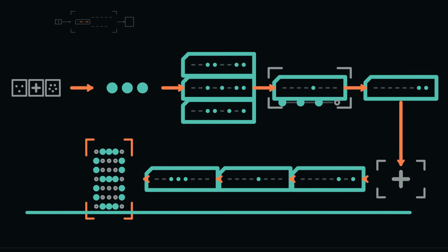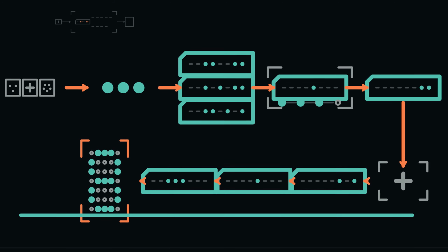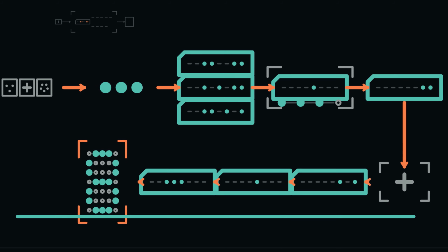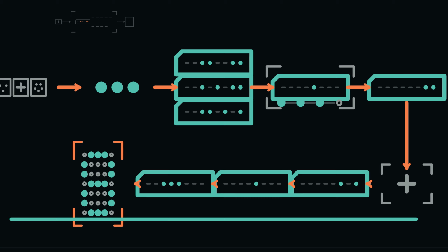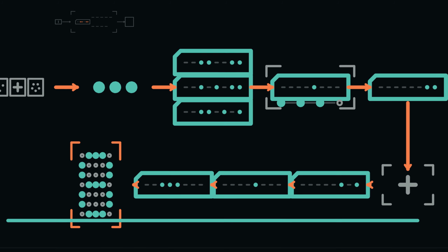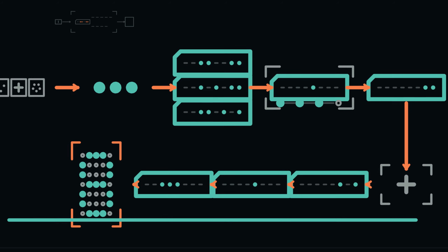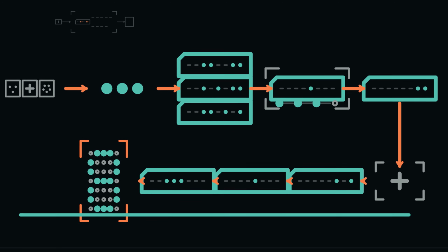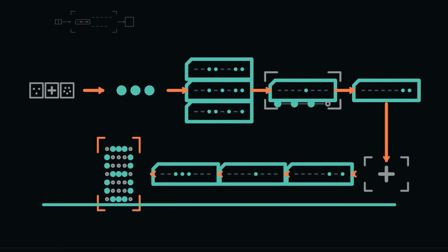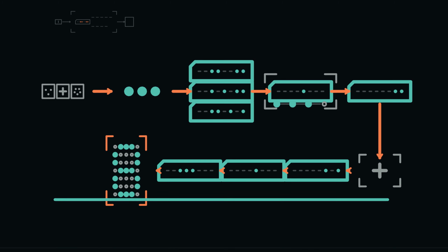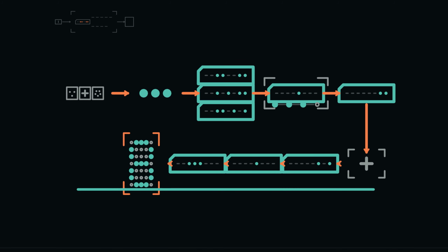The display adapter uses hexadecimal 38 to select the font entry for 8. Ordered row masks emerge from the font store. For each row, 1s select foreground pixels and 0s select background pixels at matching columns. Row after row commits until the complete bitmap is present. The visible 8 is therefore supported by a chain of selections. Output address selected the adapter, text code selected the glyph entry, row address selected the display line, and each row bit selected a pixel state.